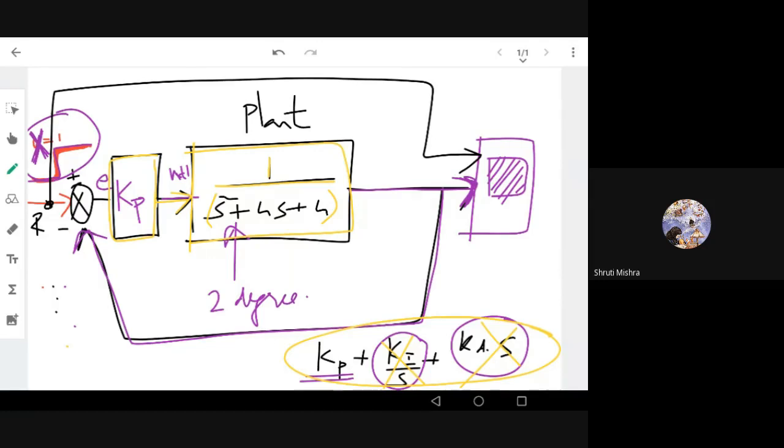Now the input to the controller is the error. Error is the output value compared with the reference value. For the reference value we are giving a step signal, something like this. Okay, so this is compared with the output, and now the proportional controller should act in such a way that it gives a plant input such that the plant output is matching your reference.